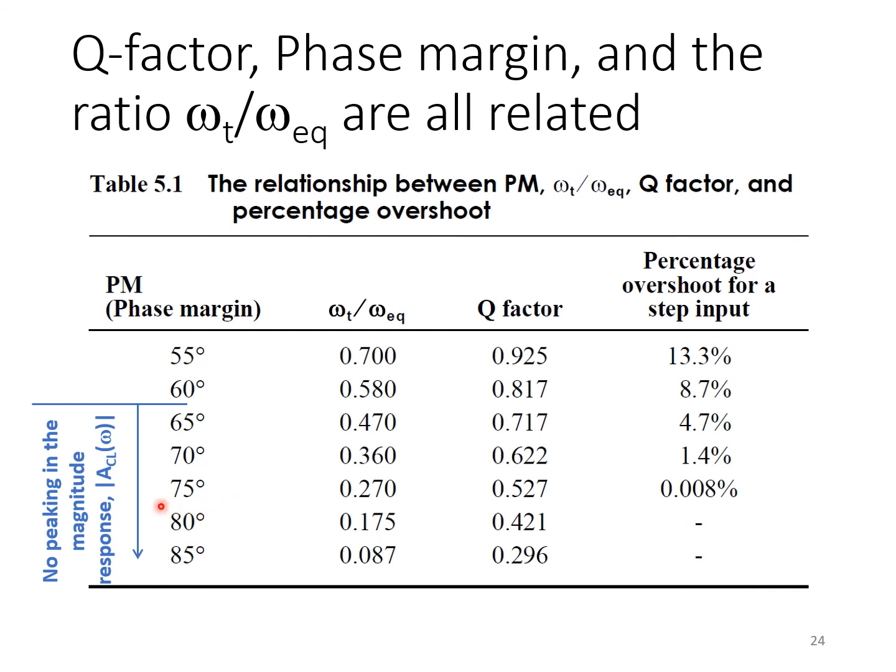And in order to do that, what it means is that we need a phase margin of about 80 degrees. So that's, again, back to this point that phase margin is not just a safety margin. If you care about overshoot in the step response of the closed loop amplifier, you may actually require a minimum of 80 degrees phase margin.